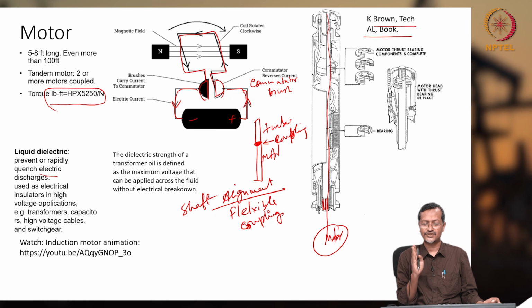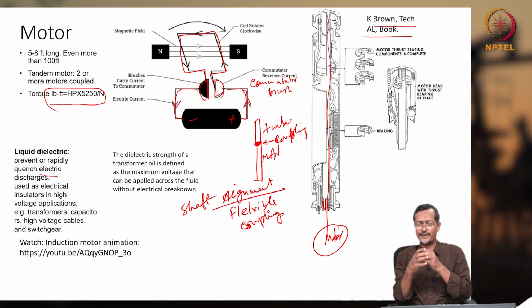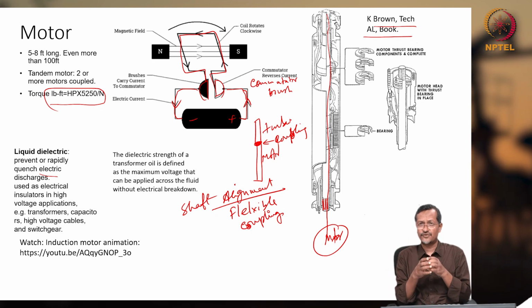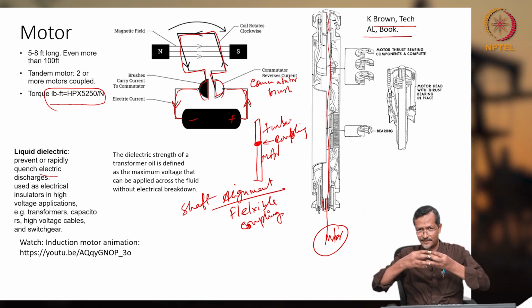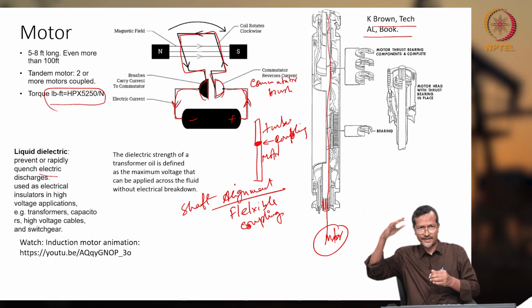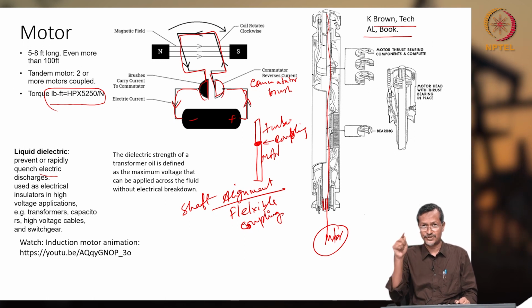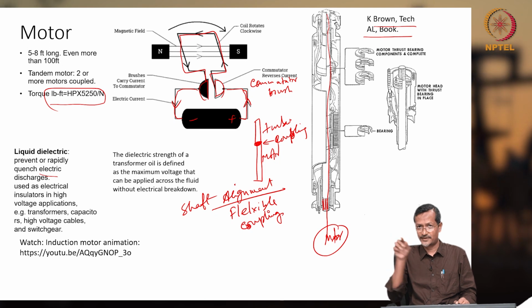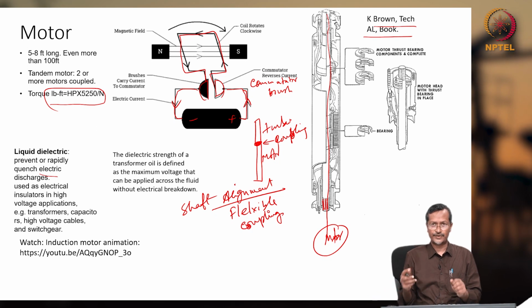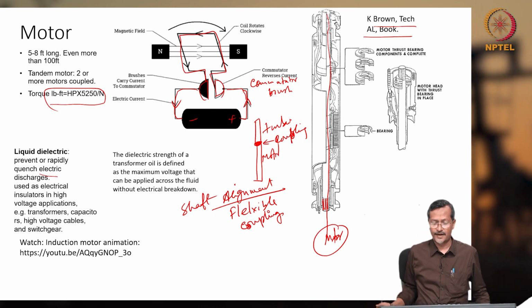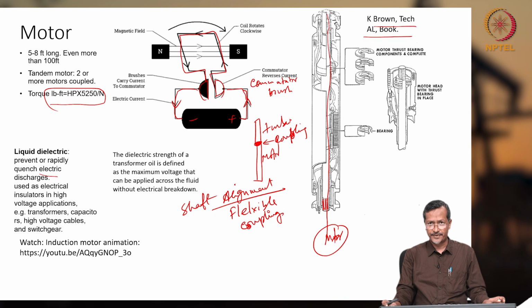Okay. So, if it is transferring any other forces, then you have to restrict them, you have to give some bearing arrangement, thrust bearing or radial bearing or flexible coupling, so that no extra force is carried from motor to your pump. If there is, then make a flexible coupling, give some extra bearing, give a thrust bearing, so that it will be transferring only torque. Torque means power, rotational speed omega times torque equals power. So, it will be transferring only torque, not any other force. Okay. So, that is why you have to give a flexible coupling, radial bearing and thrust bearing, and if possible make a shorter shaft, but it is not possible.